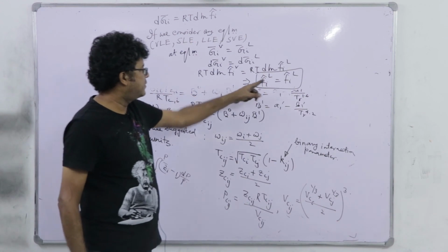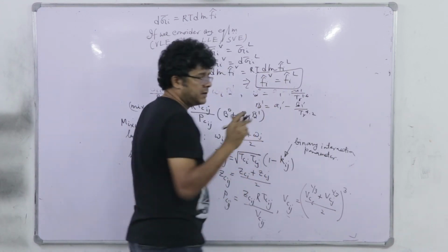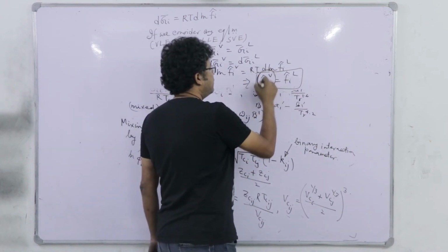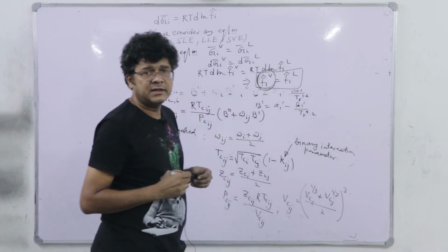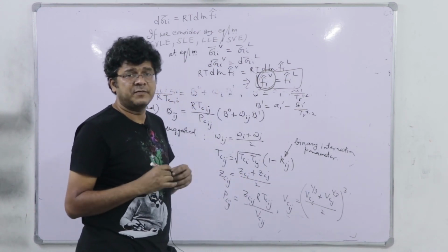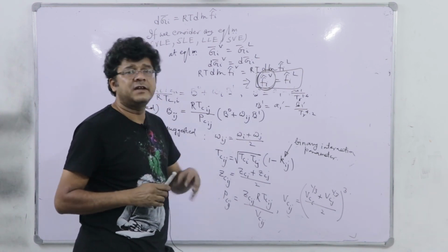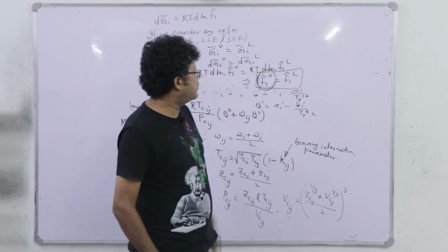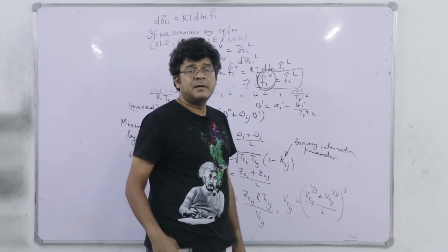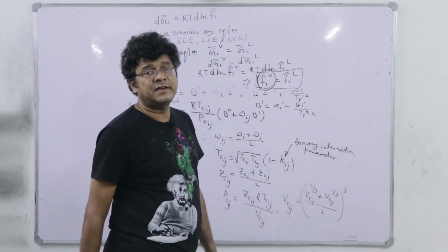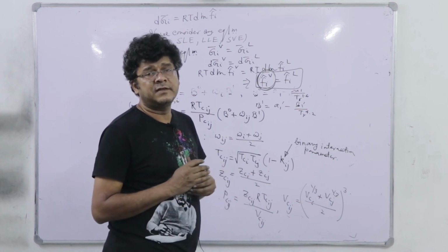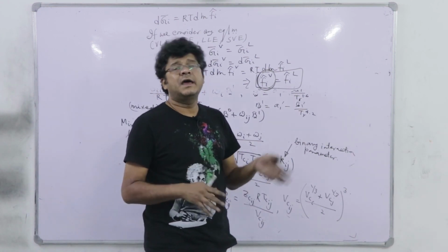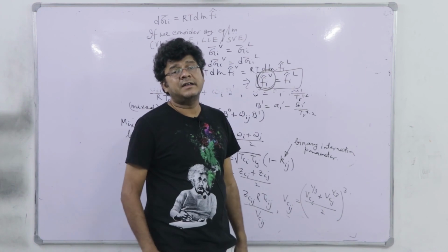So, question is, so far in this phi_i cap and the closure equation of phi_i cap, we have discussed how to calculate the component species fugacity coefficient in the vapor phase, right, because here the reference state is an ideal gas mixture and the respective property is a residual property. From there we are able to calculate this f_i cap V. But f_i cap L I will discuss in the next session, and it comes via the model of the ideal solution, and therefrom the deviation has been accounted in terms of excess property and subsequently this activity coefficient.